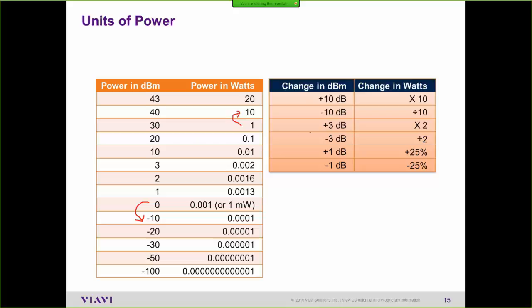When you talk about decibels, not dBm, but dB, that's a relative power number. In other words, in my equation here, that'd be the power value 1 relative to power value 2. dB doesn't say anything about the absolute power. It just says it's higher or it's lower. It just tells you how power 1 relates to power 2. But dBm, because it's referenced to a milliwatt, is actually an absolute measurement.